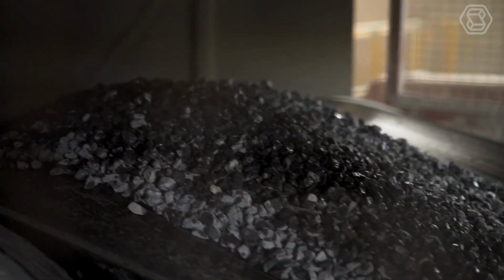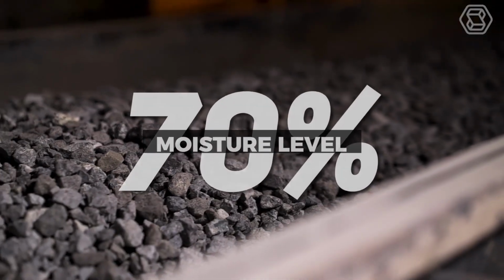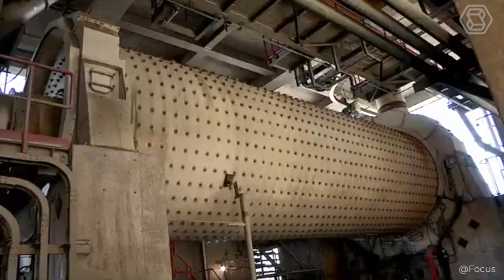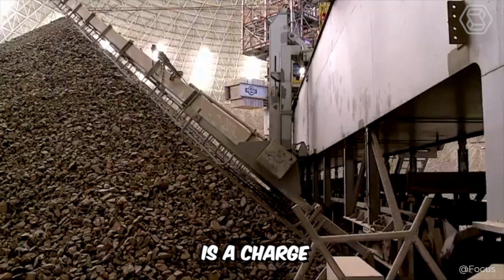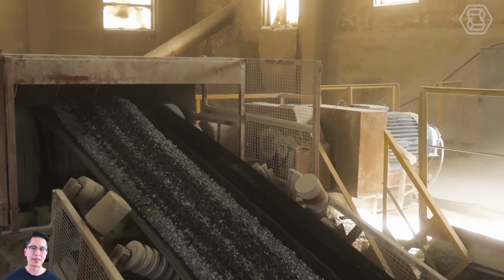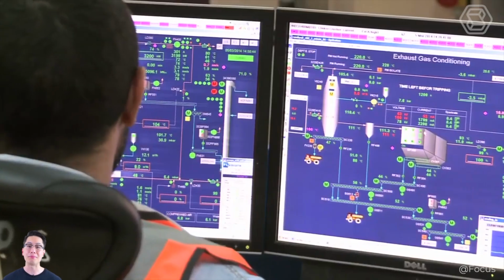The obtained composition is further sent to the mixers for further soaking. This creates a slurry with a moisture level of about 70%. The components included in the mixture are mixed and pulverized using a specified percentage of moisture. The result is a charge with a moisture level in the range of 30 to 50%. It's here, at this important stage, that quality control is mandatory.